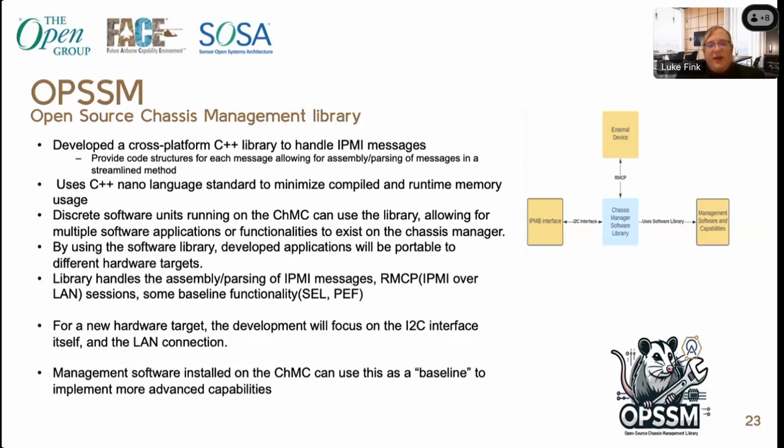The primary function of the library is to handle assembly and parsing of IPMI messages, and then a basic implementation of the sessions for IPMI over LAN, so handling authentication as well as keeping sessions up, and then some basic structures for baseline functionality, such as the system event log and platform events. So if you were to use this library on a new hardware target, the burden would be focusing on just getting the I2C interface and the LAN interface to work on that hardware, rather than rewriting code for managing IPMI itself. After that's complete, you would be able to implement advanced capabilities on top of that software.